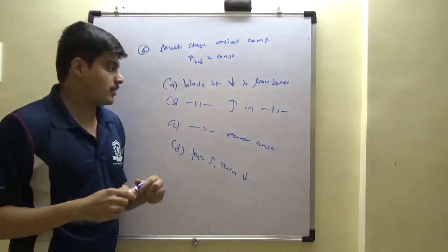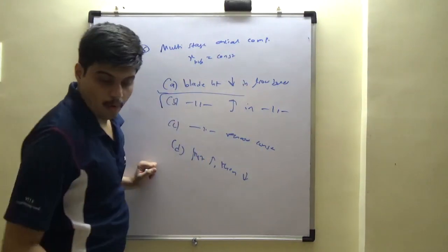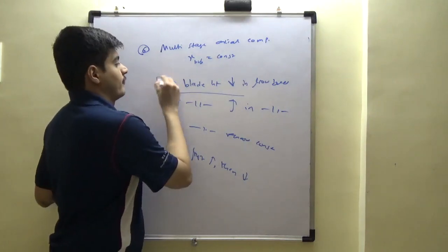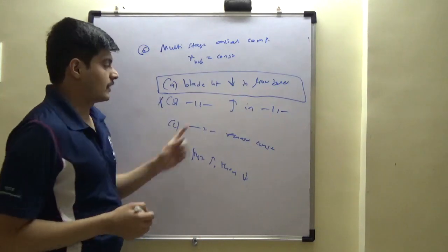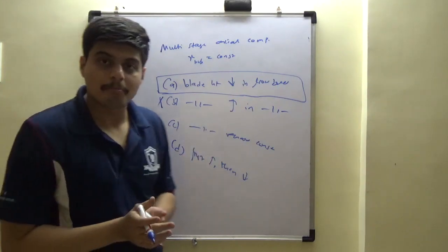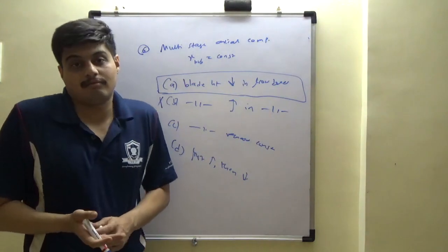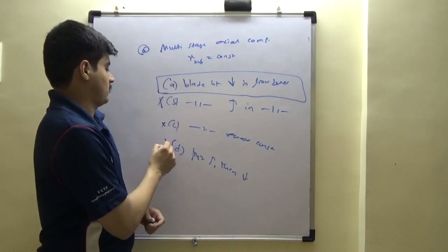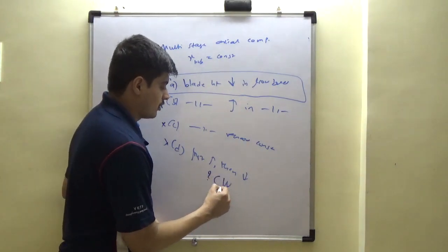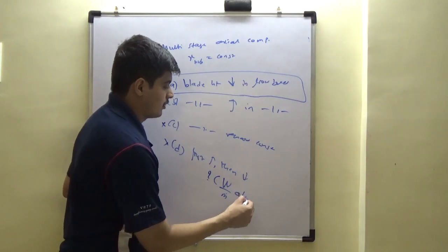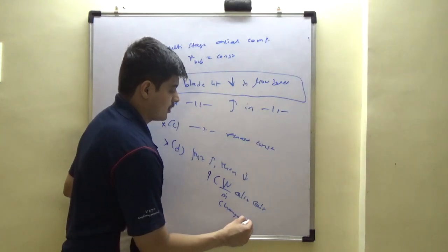Now hub is constant. Only blade height is decreasing. If you keep increasing, more work will be imparted. More work means more density. More density means more mass flow. This is abrupt. Why? W by m dot cannot change sign.